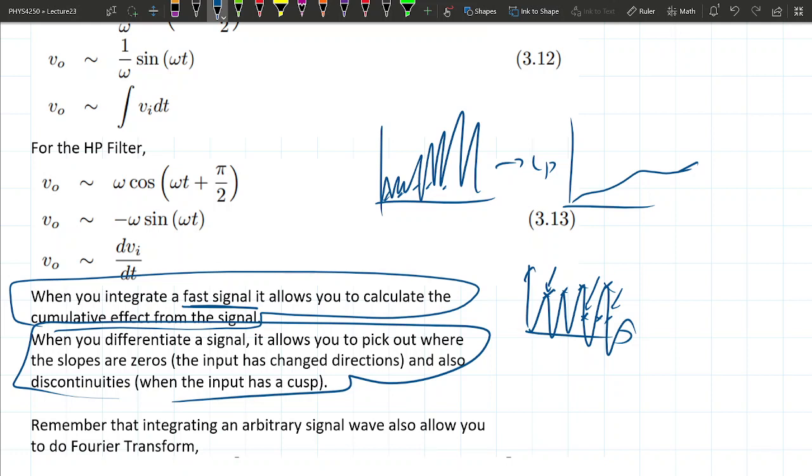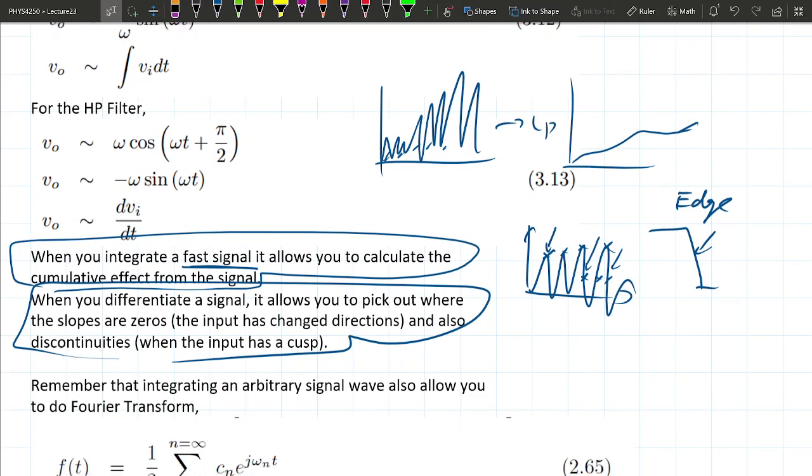And essentially, whenever you push the trigger, when you have that little trigger button and it asks for edge trigger, that little symbol here, the way it does that is by differentiating the signal and seeing that it has a very large downward slope, and that's why it triggers on it. Okay, so all these electronics happen in real time just by using a resistor and a capacitor together.